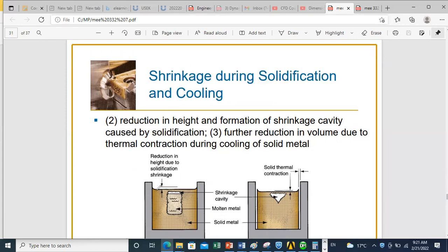You have certain parts. What determines which parts will solidify before the others? There is heat transfer with the environment. In this mold, first you have interaction with the walls, OK? You have the possibility of heat loss through the walls. So the first zone to solidify is this one, OK? And this part on top can also release heat to the environment. That's why the solidification happens in this direction or in this direction.